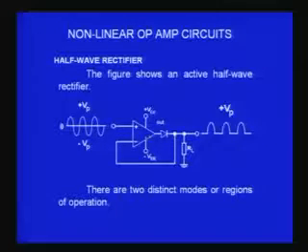So, it is an open loop condition. When the voltage increases here, this voltage will be amplified by the open loop gain of the operational amplifier, which is 10 power 5. Whatever is the voltage here will be multiplied by 10 power 5, and that will be the voltage appearing at the output terminal of the operational amplifier.